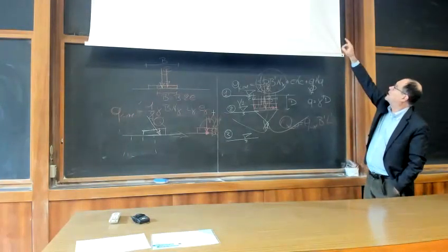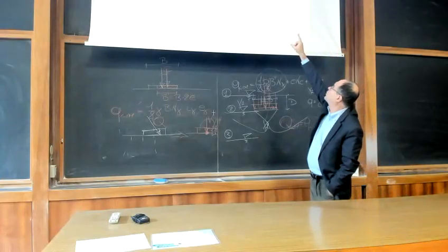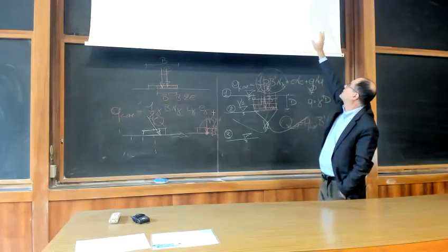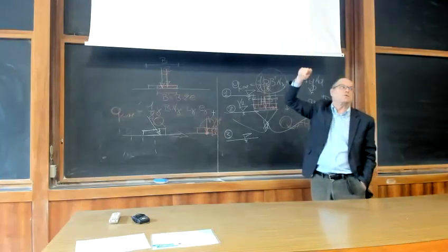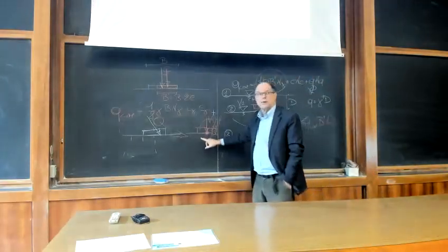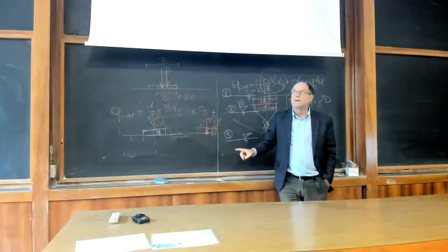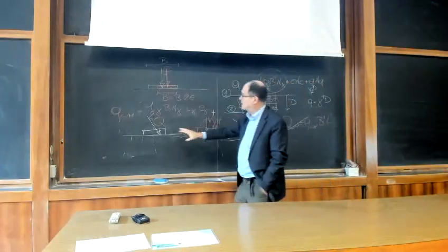Now, if you turn around that expression of I gamma in terms of H over V max, it is exactly the same expression, but just plotted in terms of interaction diagram. H and V are the two components, Vmax is the maximum capacity.